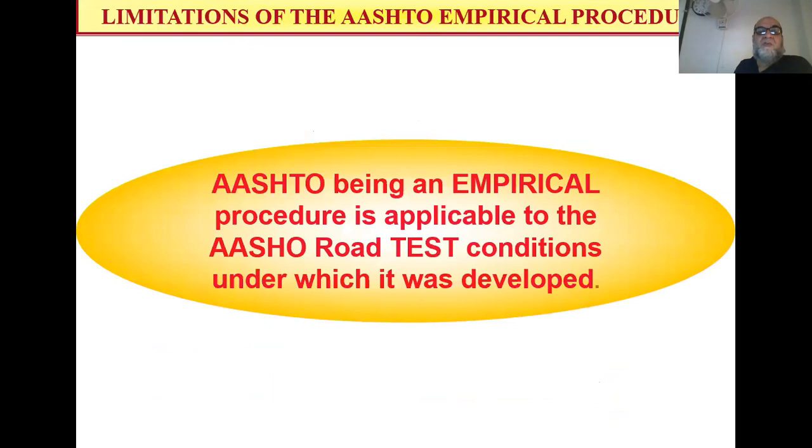So the problem with AASHO is that it is an empirical procedure applied to the AASHO road test conditions under which it was developed. So if a model that is developed somewhere else is applied somewhere else, it always gets the problem like we have.